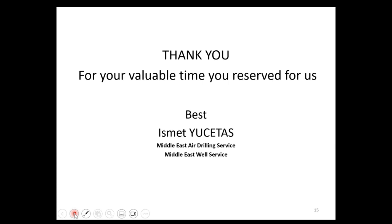But I know that there is some certain closed loop system. In order to decrease the closed loop system surface pressure or energy consumption, a secondary stream could be lowered down in the production well to re-inject CO2 to make a natural, like a gas lift.